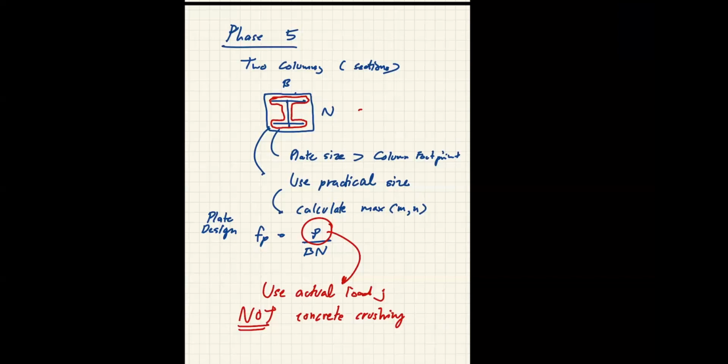In practice, when we weld the base plate, it's not a bolt anymore, right? How can you attach the base plate to the column? Yeah, I see. When you have the base plate at the end, you can use bolts to adjust the leveling of the column during erection. Like anchor bolts, right? Yeah, anchor bolts, exactly.